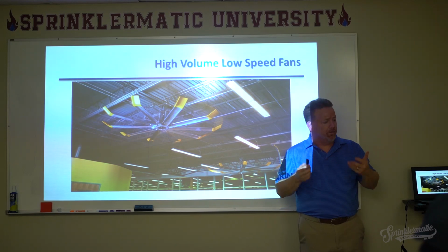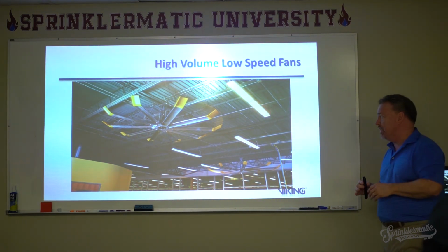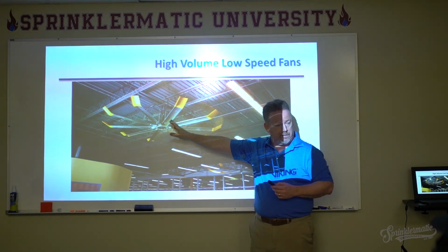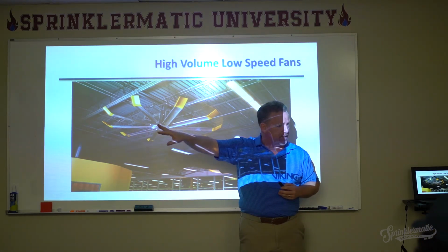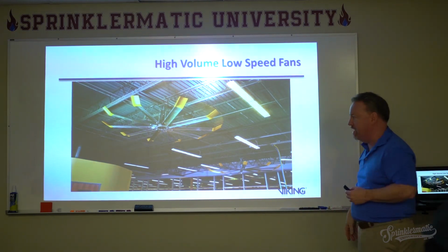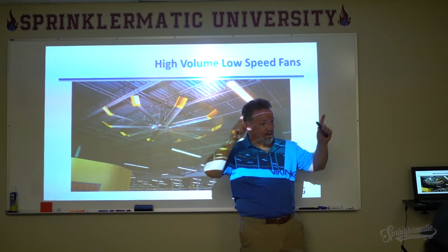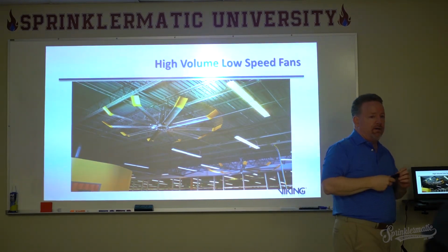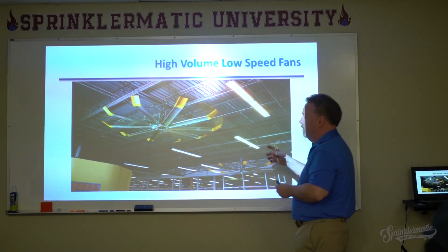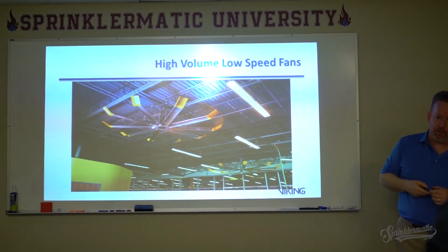The answer, in a research project that was done, is not so much, as long as the fan stops before it shuts down with the alarm. The detection system shuts the fan down, and you have, as far as ESFRs are concerned, sprinklers spaced equally around that particular unit. We can treat this simply by standard obstruction rules at that particular point.